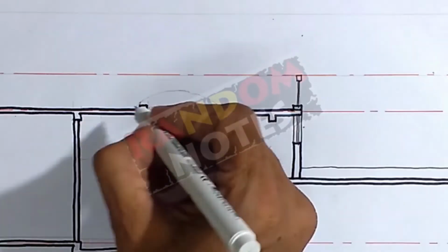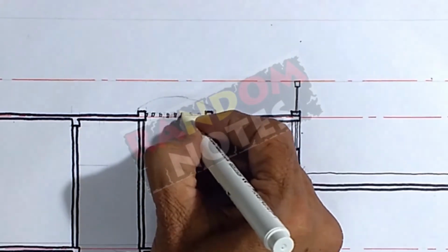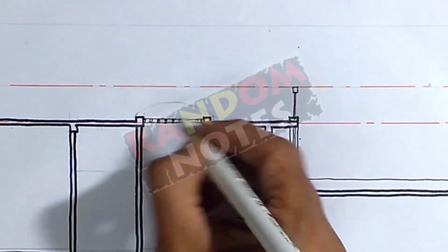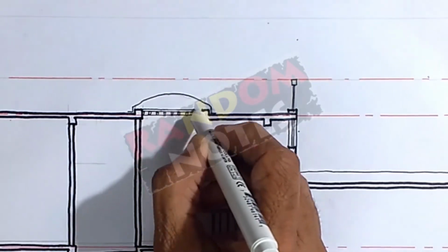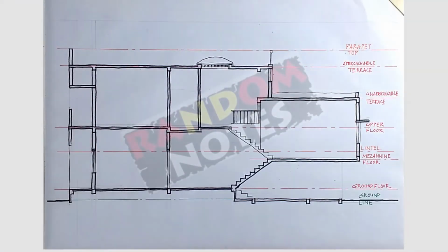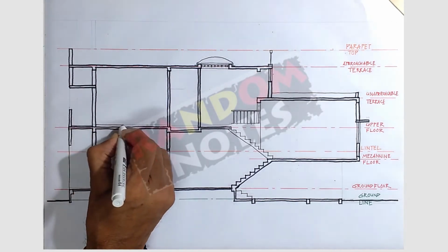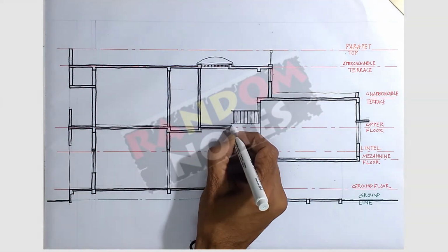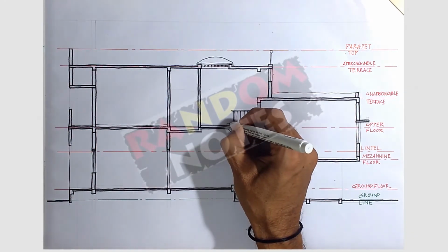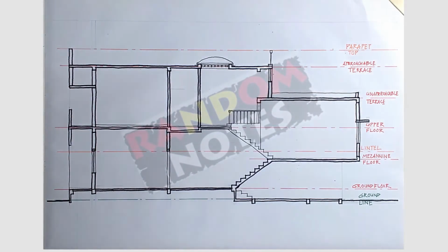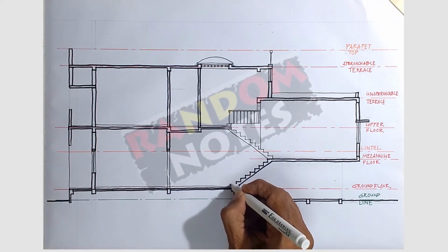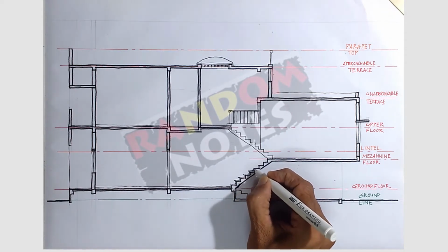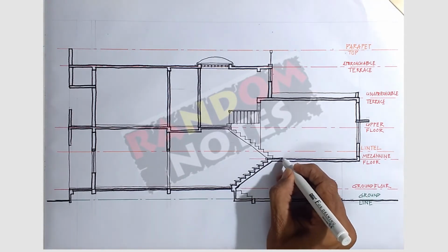This is a cutout which is open to sky and has mild steel security grille and a fiberglass or a similar material cover. All the elevational edges have also been drawn. All floor surface will have floor finish which is conventionally taken as 40 to 50 mm thick, including the base and the flooring material. All floors are laid at desired level and with the desired slope if needed.